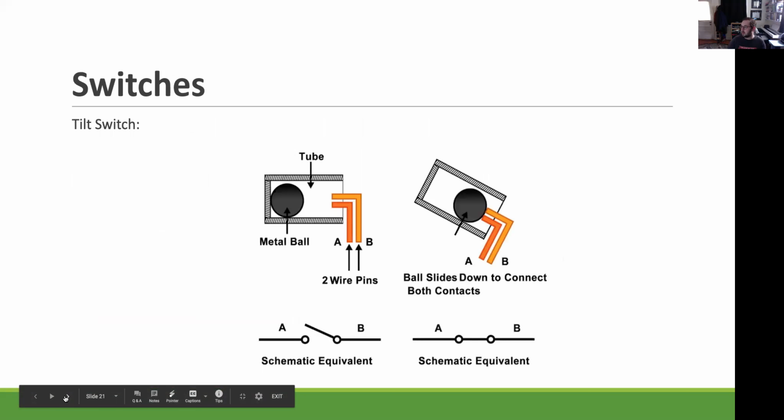There's also what's called a tilt switch. You have your signal coming in and then going out. It goes in A, comes out B. As you tilt it, this metallic ball connects to both of them, and because metal is a good conductor, the electrical current will pass through A to the ball, out B. So it'll only happen once you've tilted it so that you can connect things. That's a good way of making some interactive items. To a degree, unless you have digital ones, that's how some old school tilt sensors and gyroscopic type things would work.